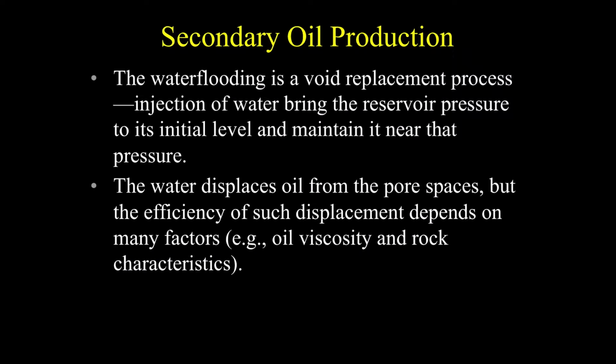How the water flood works. The water flooding is a void replacement process. Injection of water brings the reservoir pressure to its initial level and maintains it near that pressure. The water displaces oil from the pore spaces, but the efficiency of such displacement depends on many factors, for example, oil viscosity and rock characteristics.